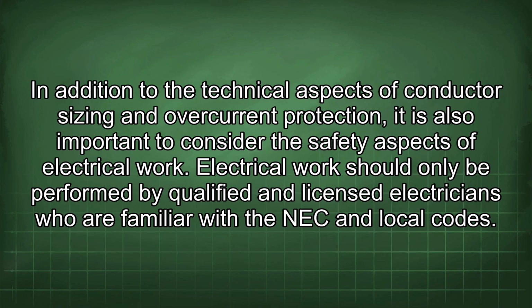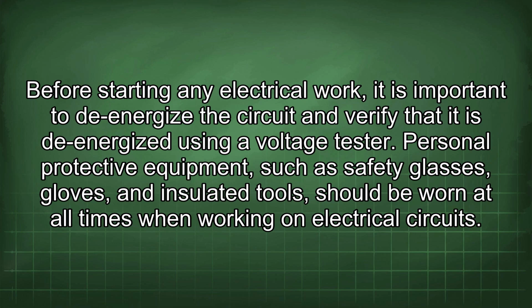In addition to the technical aspects of conductor sizing and overcurrent protection, it is also important to consider the safety aspects of electrical work. Electrical work should only be performed by qualified and licensed electricians who are familiar with the NEC and local codes. Before starting any electrical work, it is important to de-energize the circuit and verify that it is de-energized using a voltage tester.